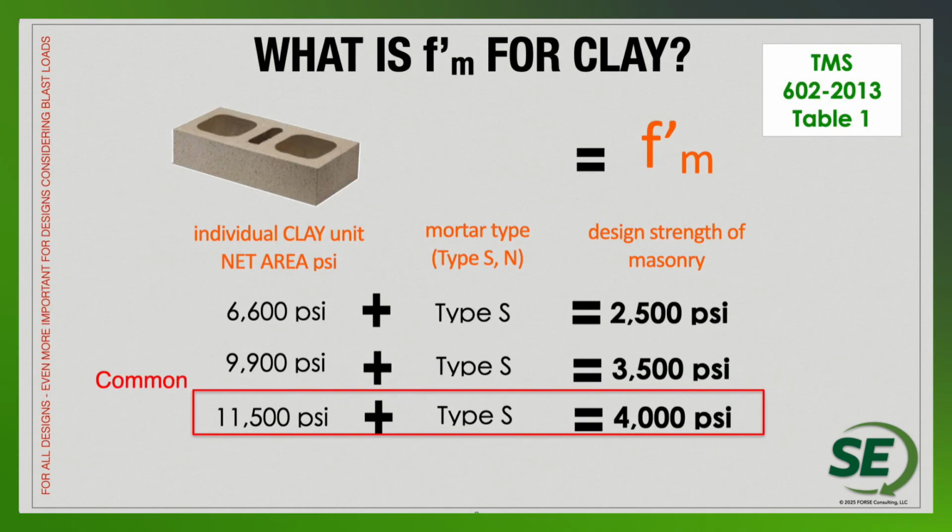And certainly you have another material in masonry: clay, structural clay units. It's not necessarily the emphasis of what we're talking about today, but structural clay is even stronger than concrete masonry, or as strong as some of the higher strength concrete that we can specify. But again, this is another option if we need to go to a higher strength f'm. We certainly have materials available, either high strength concrete or clay, where we can approach a strength of masonry of 4,000 PSI.